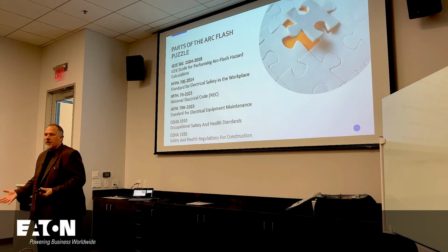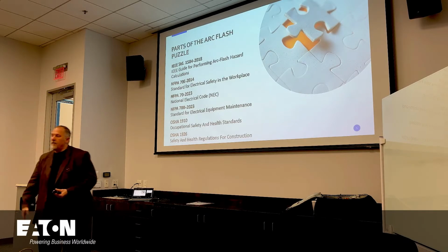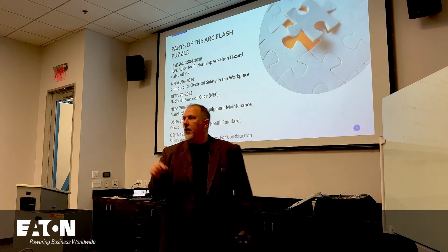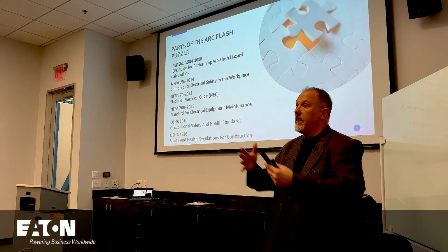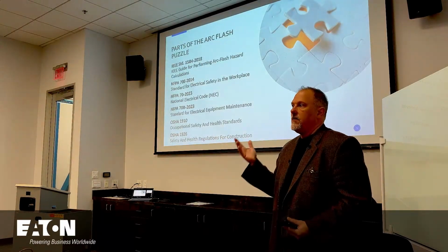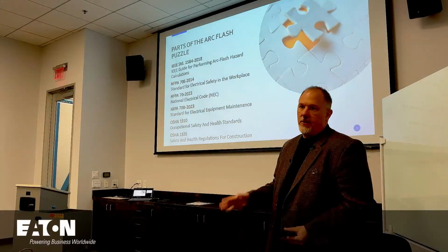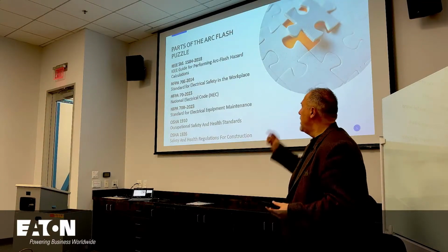Can't measure how much shrapnel because I'm not testing in equipment. And the argument from many manufacturers is that, well, when you have that same arc flash event in equipment, you're not going to have the same results. It's probably going to be a lot less because of the spacing and everything else. But we can't get the testing in everybody's equipment because it would just be way too expensive, right? Because there's so many configurations.